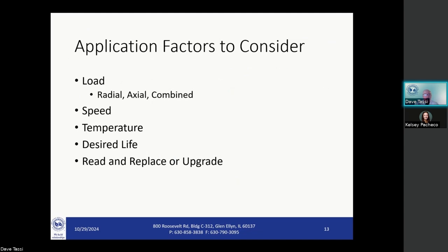Know what the speeds are, generally in revolutions per minute. Know how hot an application will get. Depending on the temperature, you may have to use special materials or special bearings to accept those temperatures. Know how long you want that bearing to last.